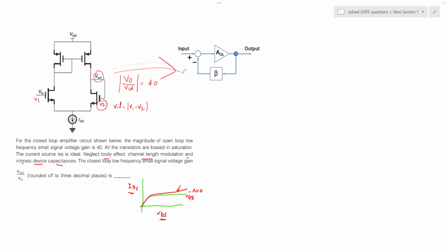This circuit diagram is represented by this block diagram where you have got the input, and the input here goes to your mixer. The job of the mixer is to add or take a difference of the two signals at its input. If it takes the difference between the two signals, that is the input and the output being fed back to the input, this system is called a negative feedback system.